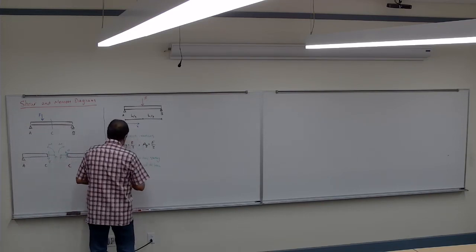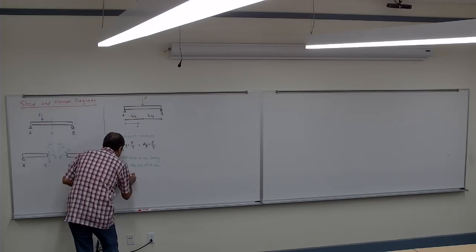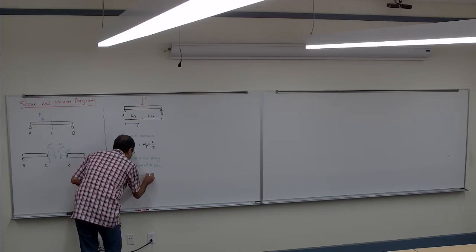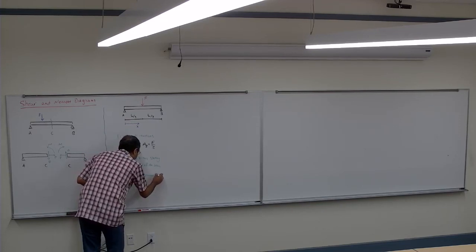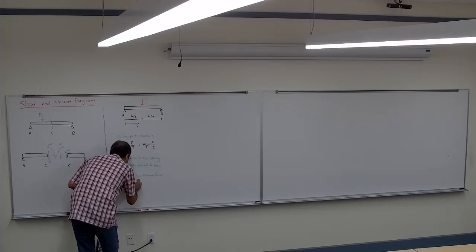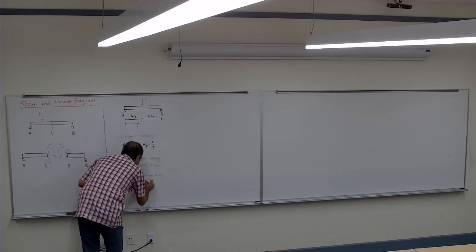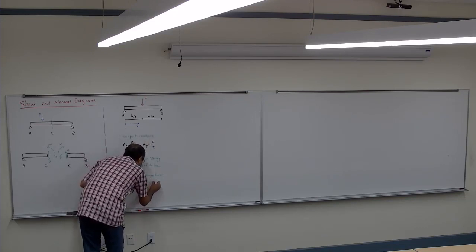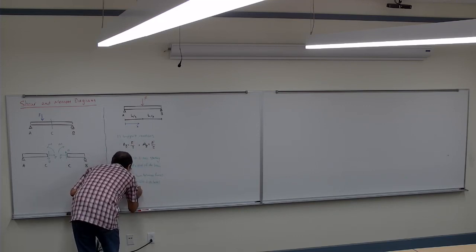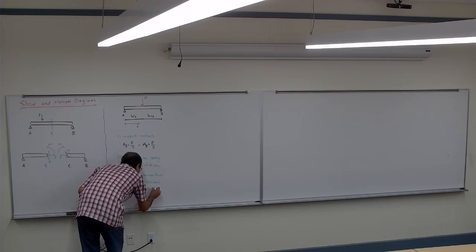And then the third step is to cut the beam between forces, or in the middle of a distributed load, to find internal forces.